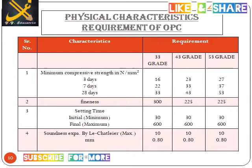Now look at the 43 grade cement. In 3 days it achieves 23 Newton per mm square compressive strength. In 7 days it becomes 33 Newton per mm square, and in 28 days it becomes 43 Newton per mm square.